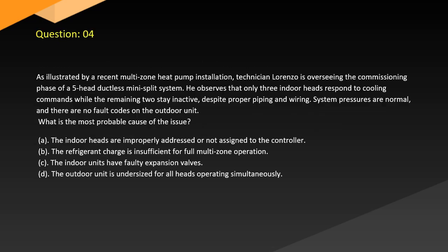Question 4. As illustrated by a recent multi-zone heat pump installation, technician Lorenzo is overseeing the commissioning phase of a 5-head ductless mini-split system. He observes that only 3 indoor heads respond to cooling commands while the remaining 2 stay inactive despite proper piping and wiring. System pressures are normal, and there are no fault codes on the outdoor unit. What is the most probable cause of the issue?